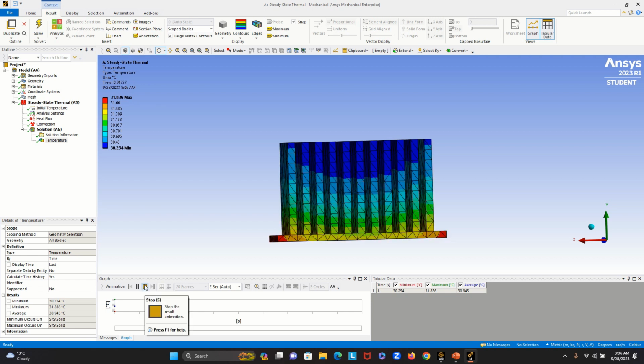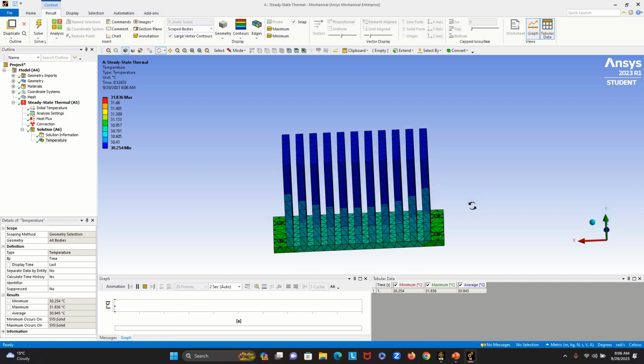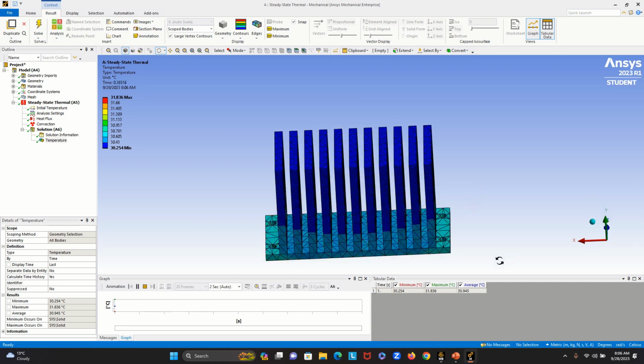Next, we're going to have to do the same thing with the 5 fins as well. In order to do that, we have to calculate the surface area, and we're going to have the same model, same design with the same thickness. The diameter for the holes will be the same, the gap from the hole to the first fins will be the same on both sides, and the width, length and thickness, I mean everything for the fins will be the same. The only things that will change are the number of fins and the gap between the fins.